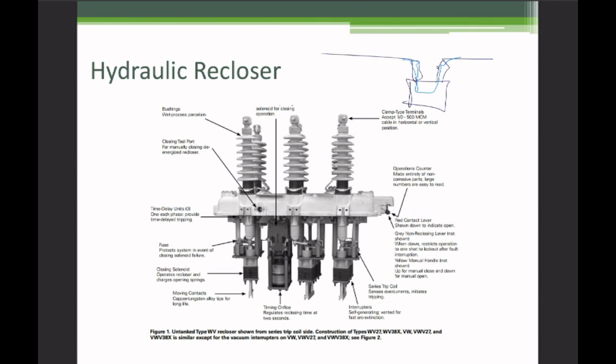It's important to note that these are not programmable. The way you change the settings on one of these is you get in there and you start changing parts. If you want to change the timing, there's the cylinder that, when things pulse, fills this tank. If you want to change how long it takes for the tank to empty, you change how big the hole is, the timing orifice. So, very difficult to change the settings on.